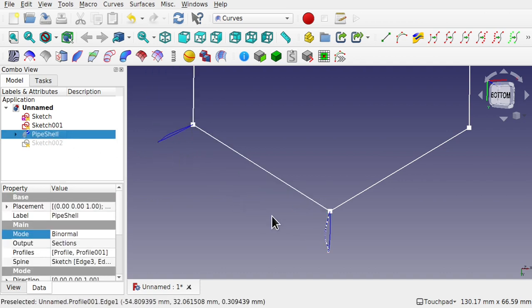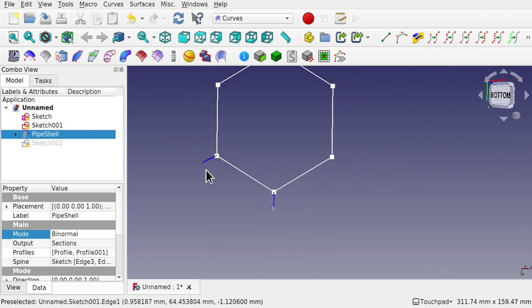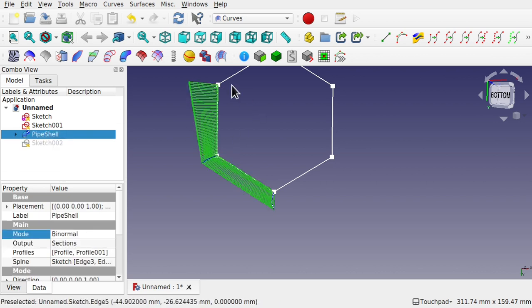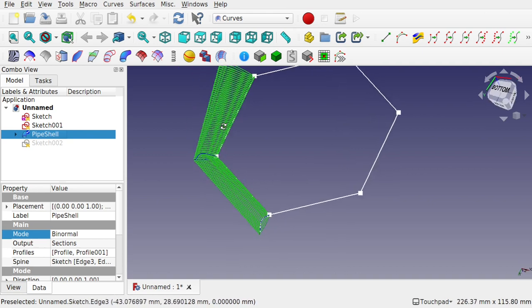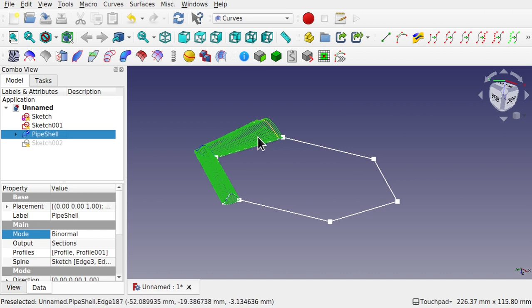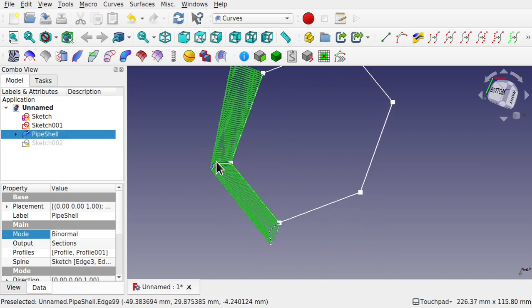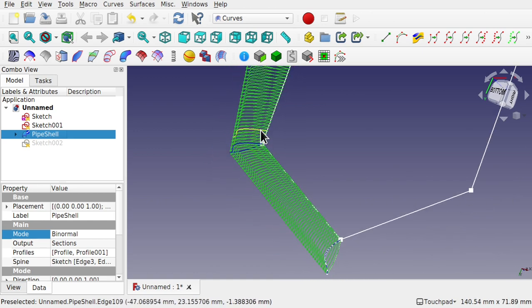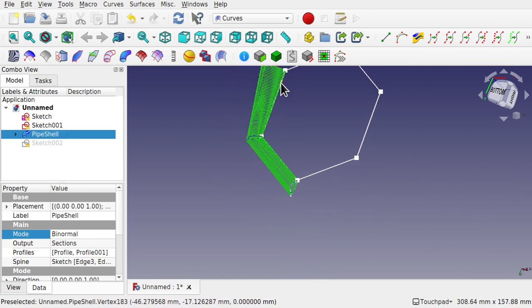You can see there's a line that goes along here. This one, we took the edge up from that and out, then we're going off into the distance. So just be wary of that when you haven't got an ending profile and they splay out like so. Just put another profile in there and it brings it back. Don't have to have the same profiles. We can have different profiles along here. So if we want to shrink this down a bit or even change the shape of this profile entirely, we can place that in here as well.